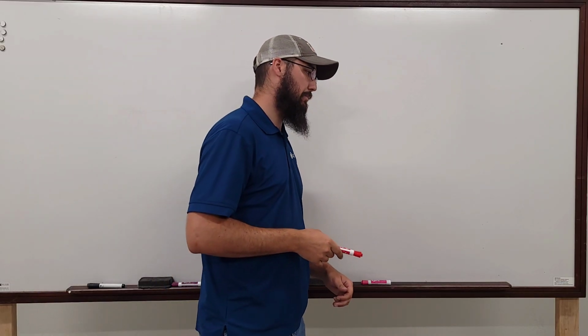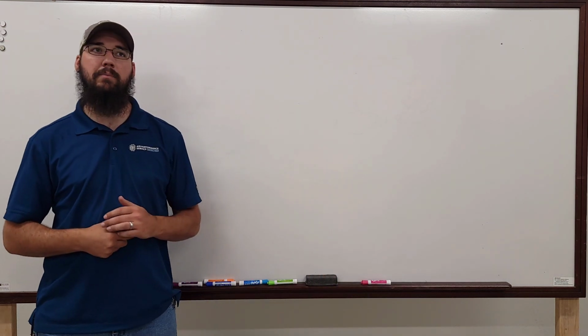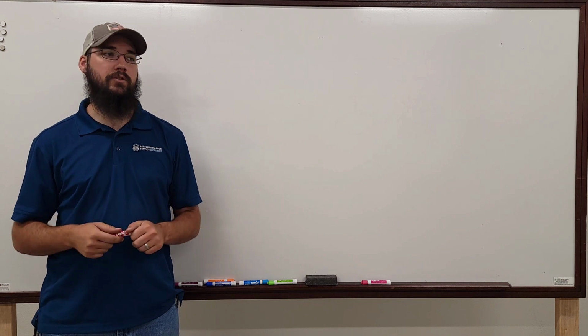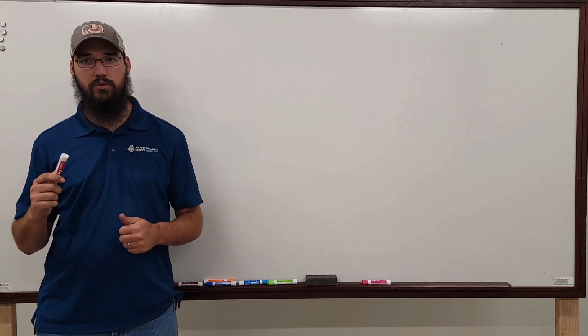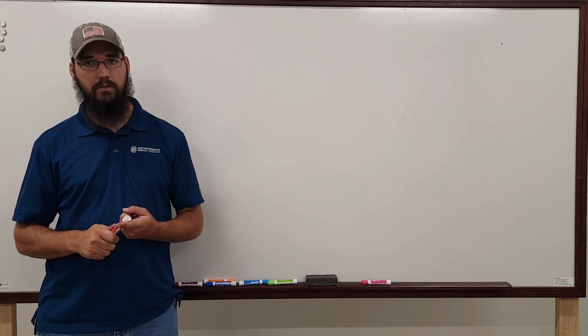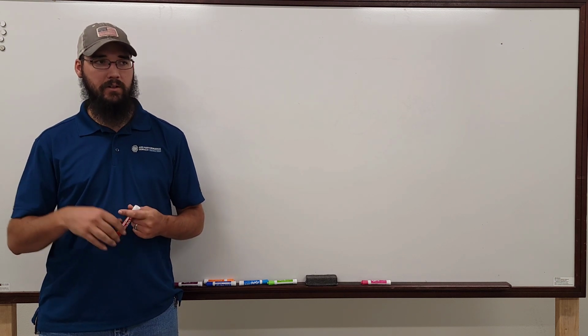Pumps. Pumps are pretty straightforward. The big thing about pumps is, all the same principles apply. Where people get in trouble is controlling the building loop pressure and not running too much pressure.